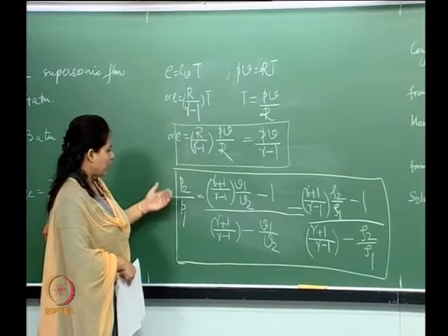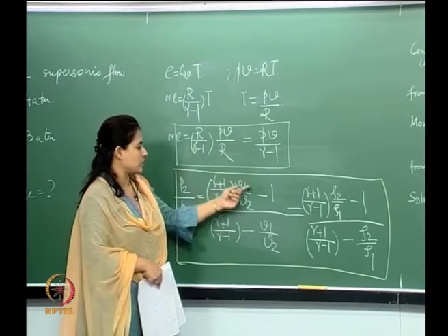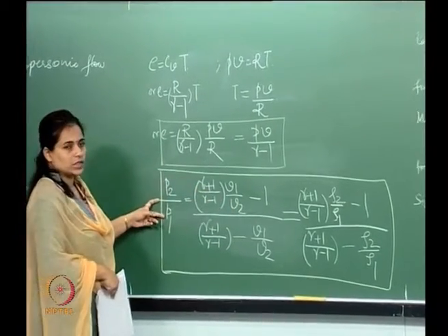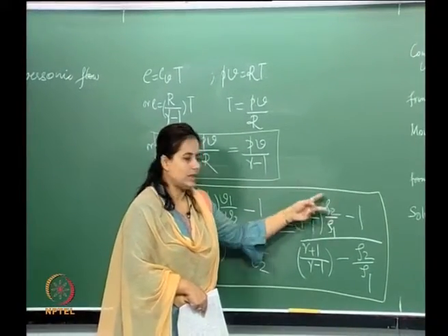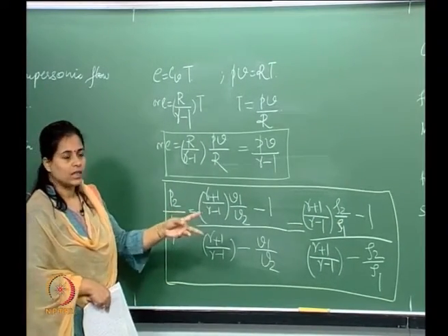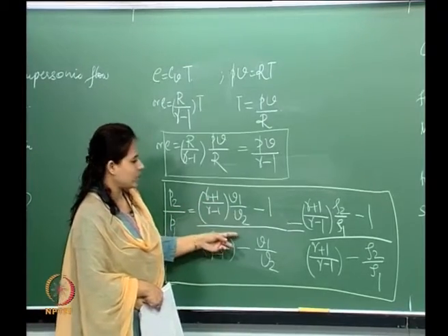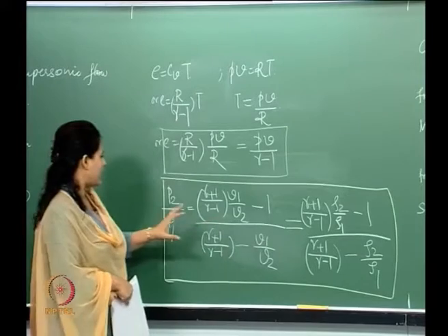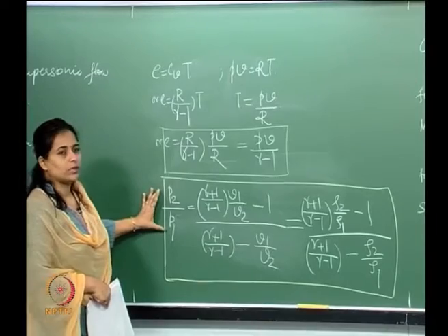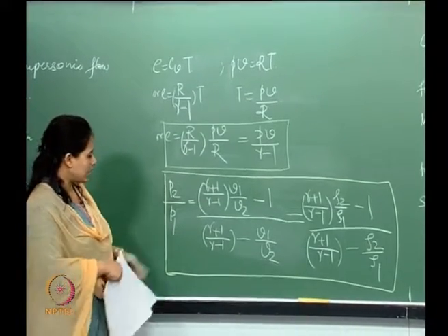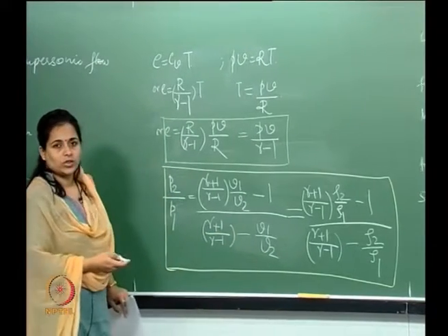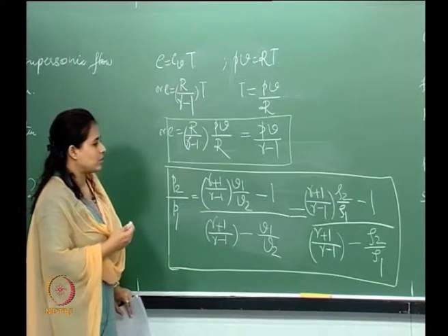is the way the specific volumes change, with a particular value of specific volume, the pressure will change. With this particular range of density changes, how the pressure will change. So, essentially if I were to plot this for various values of V1 by V2 or rho 2 by rho 1, then I will basically get a curve which is telling me how the corresponding pressures are changing. Okay. Now this basic expression is called the Rankine-Hugoniot relationship, and I would suggest